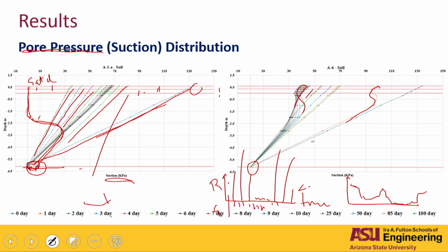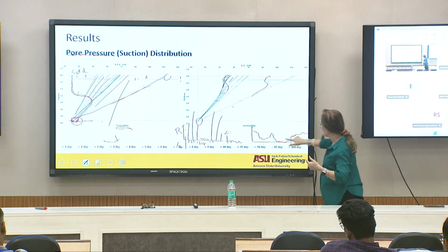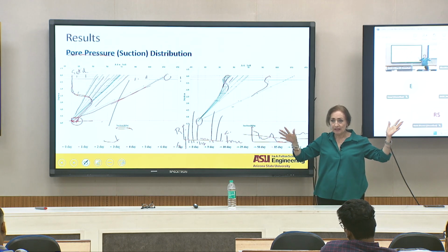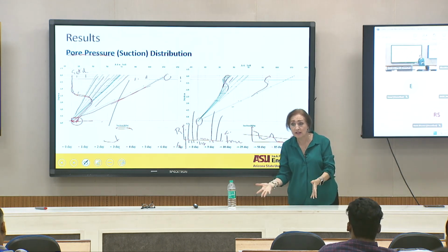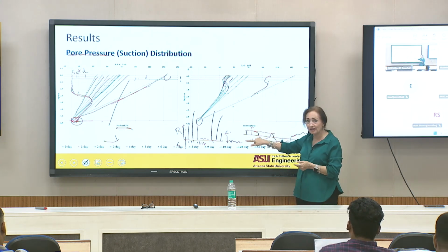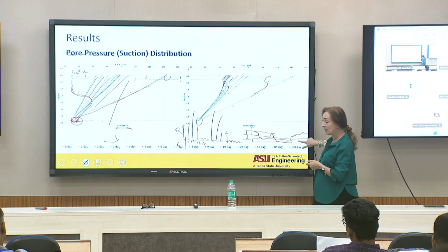Eventually, if you are designing a road for 30 years, ideally what you want to do is to figure out what is the average value that's going to happen. But if you want to include a little bit, this one is prone to flooding conditions, you're probably going to be adding a percentage in here or a percentage down here and design for a value in here.